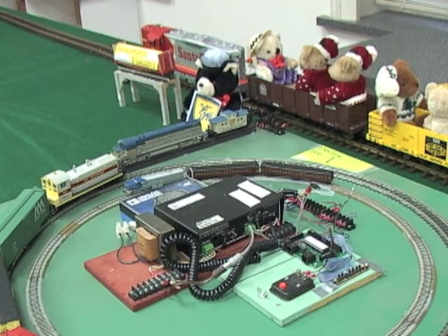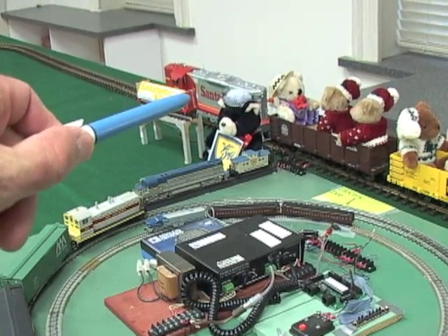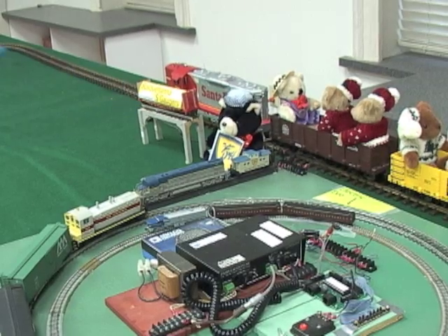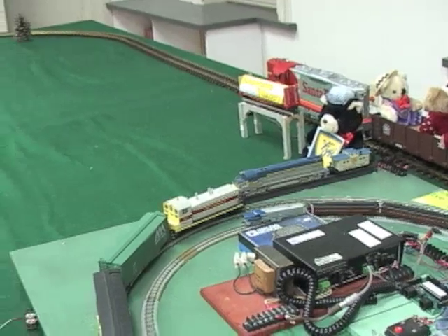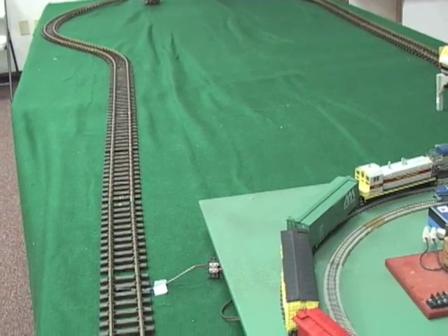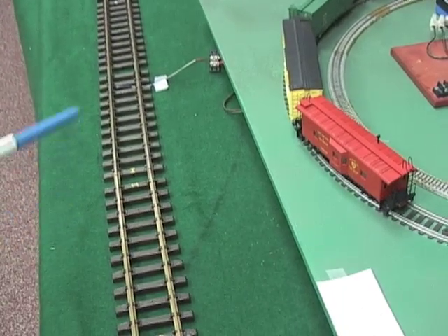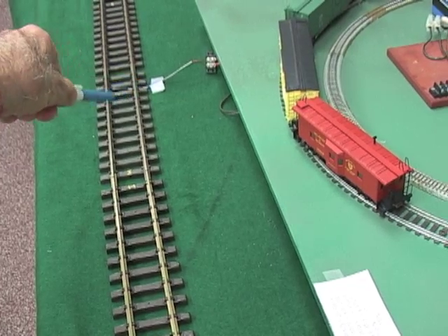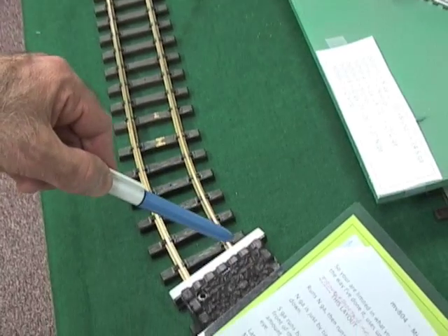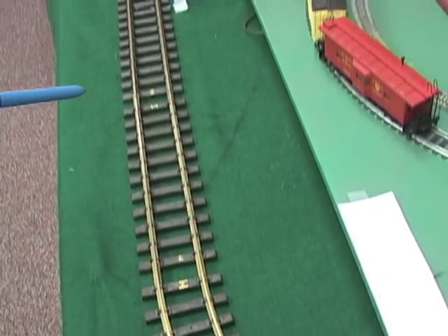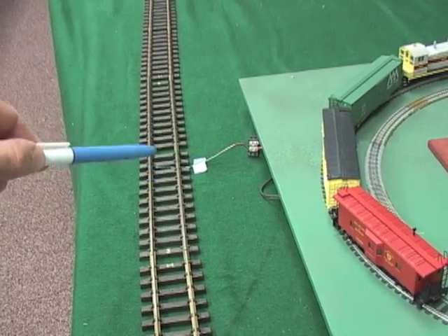That's why I do a delay when, for example, the large scale engine over there starts up. I do a delay statement to get it going for a while, and I blow the horn. I do that fairly early in the process, but when it comes around the track and it's coming down to the end of the track, if it's in a delay statement, it goes over that reed switch there, it won't see it. It would crash right into the end of the track here. So I have to make sure it's not in a delay statement, that it's actually actively looking for new inputs.